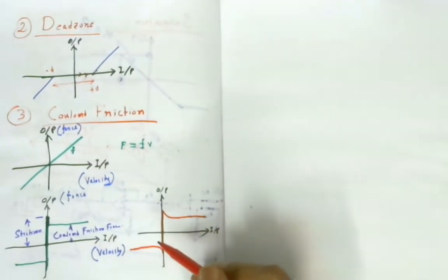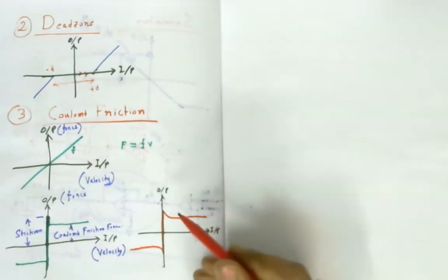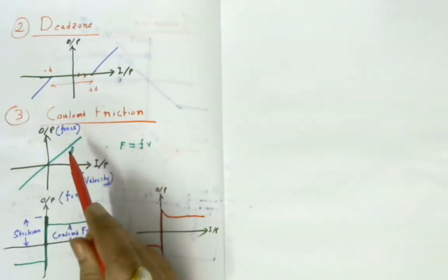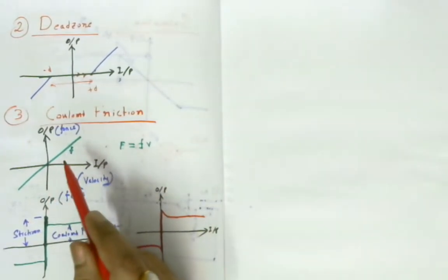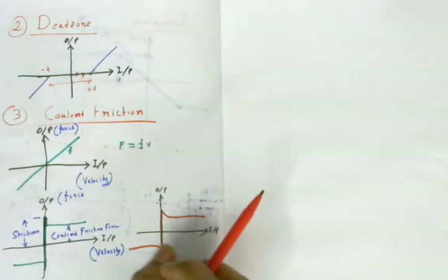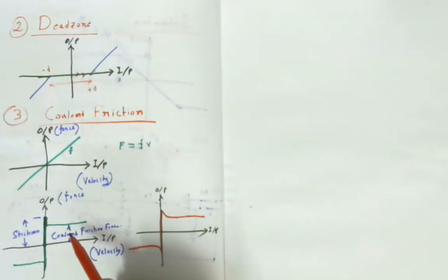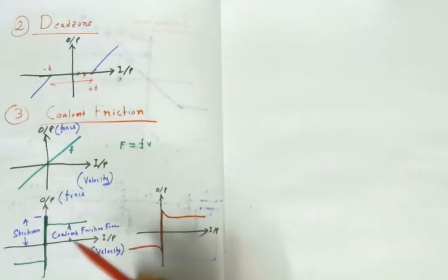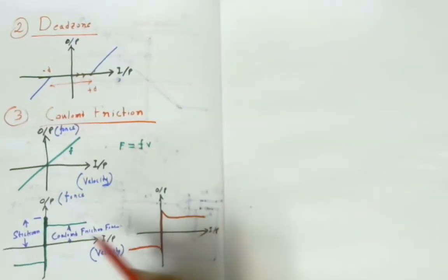Now as a whole, this figure is not linear; it does not represent a straight line. However, the viscous friction was a straight line, but viscous friction is one part of the friction force between the two sliding surfaces. The Coulomb friction force is another part of the frictional force, and before the Coulomb friction force happens, there is an initial force which is called the stiction force.